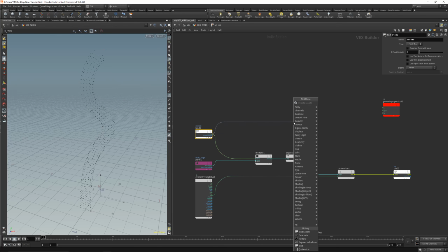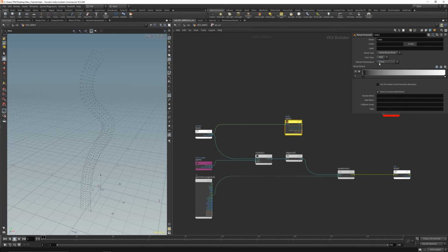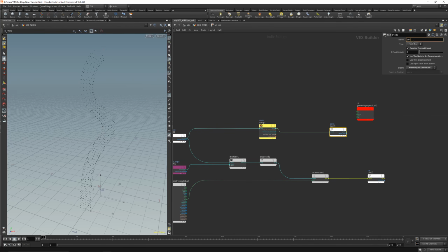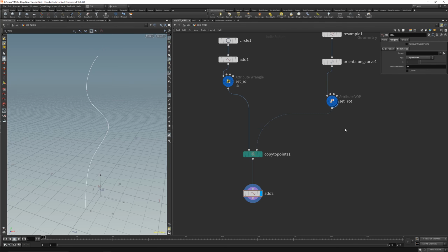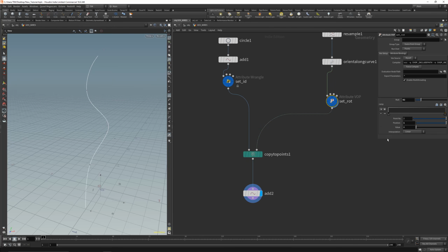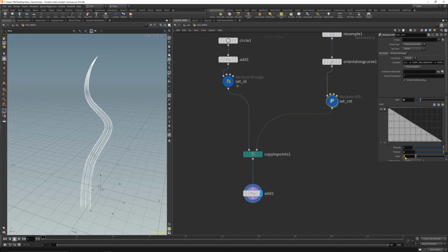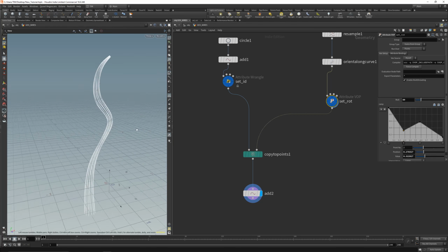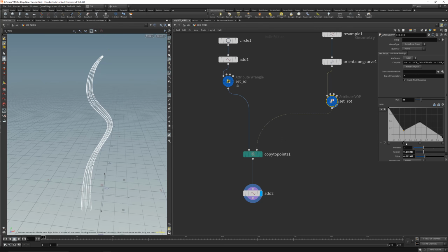Sorry for that guys. So we already did this, but now we want to do another thing. We want to use the curve view with a ramp, with a spline ramp, and bind that out for our Pscale. Let's go to our ramp here. And now we can influence our Pscale. That's really nice. We've got our rotation here and our Pscale, so you can change it however you want. Let's just leave it like that. I like that.